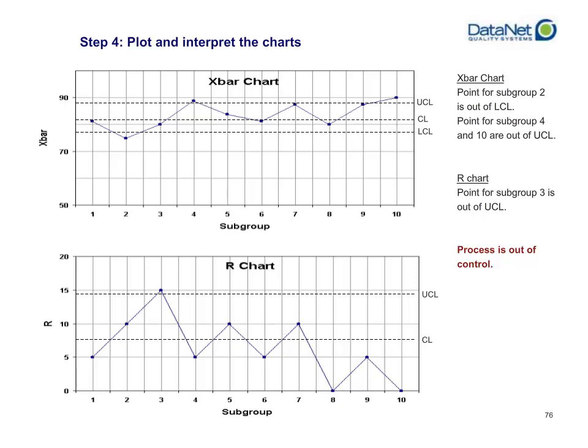And just eyeballing the trend after that, it looks like things were getting worse from subgroup 1 to subgroup 3 with regards to volatility. But all of a sudden, maybe a change happened in the middle of that subgroup, around 11 a.m., and then things started getting better, and your volatility starts to go way down until you actually have no range, no variation at all, on subgroup number 8 or subgroup number 10. So your volatility within your process seems to actually be getting better.